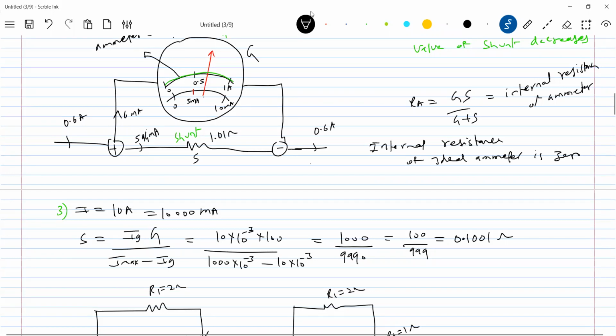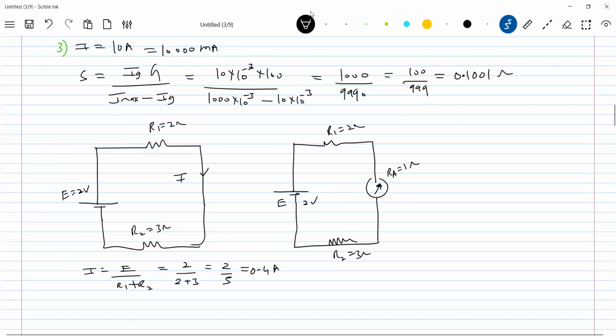Is it ideal if I mention it, then wherever the ammeter is there, you can put a short circuit. But here I wrote ammeter 1 ohm. What do you mean by that? So when you are doing a problem, just replace the ammeter with a 1 ohm resistance. R2, R1, and this is RA. How much? 1 ohm. And carry on the problem.